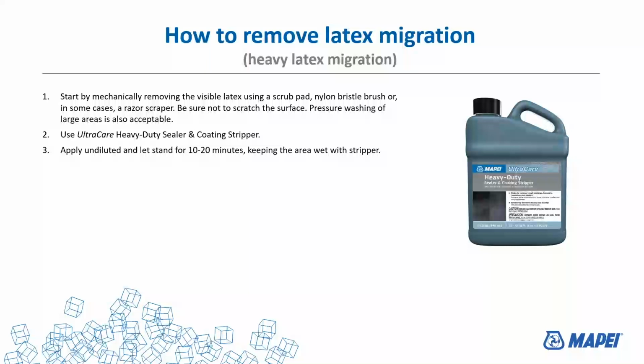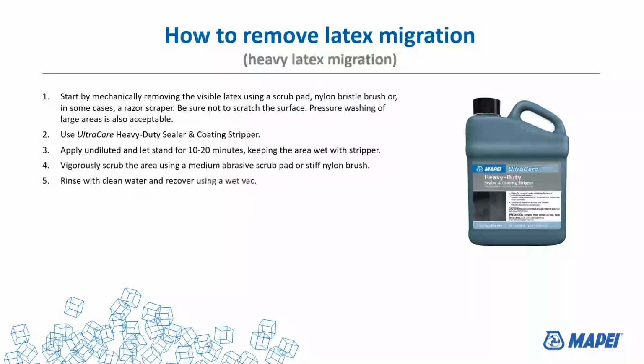Again, hit it hard with the scrub pad or a brush, and rinse with the clean water. Use the wet vac, and dry with the clean towel. Repeat if needed. So both of these are good methods to remove latex migration.